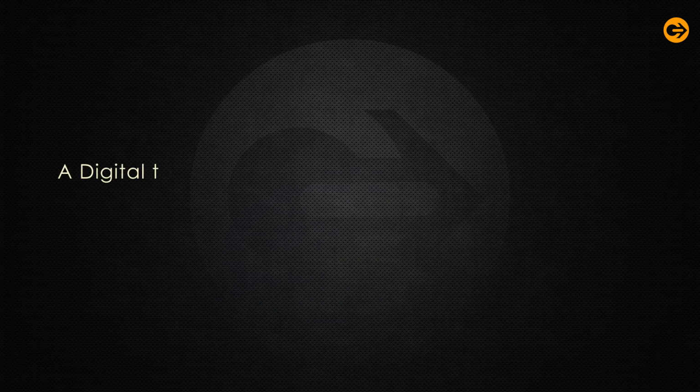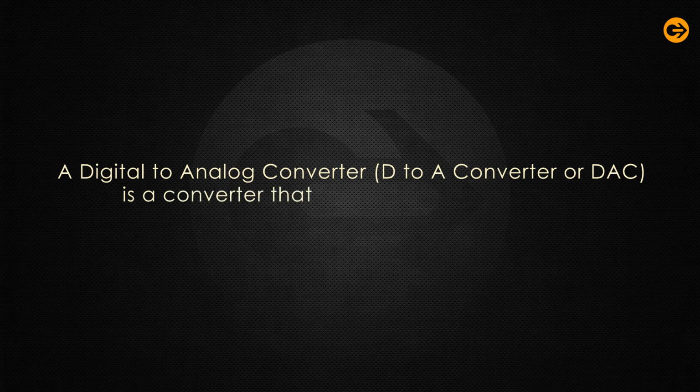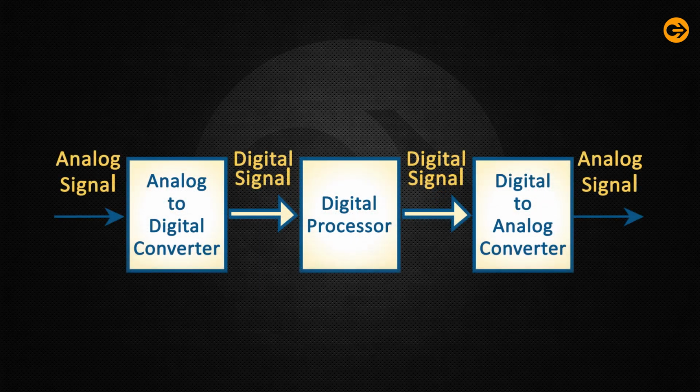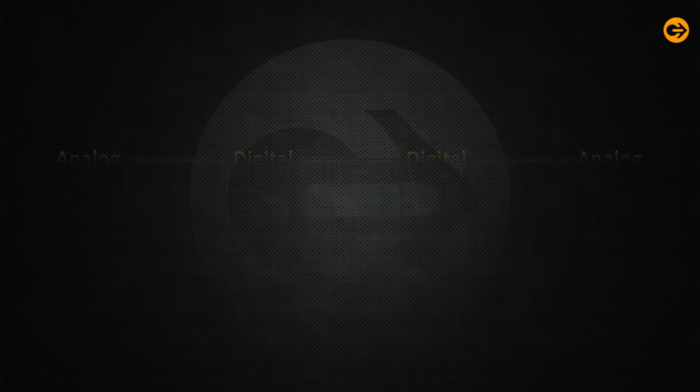Today we are going to learn the primary segment of DAC. A digital to analog converter, which is D2A converter or DAC, is a converter that converts digital signals to analog signals. The DAC has digital input and analog output. They are used in television and mobile phones where the digital video data is converted to analog video signals. Here, the output of a system may be required in the analog form, thus converting the digital output to analog form. The input of a DAC is an n-bit binary signal in a parallel form.